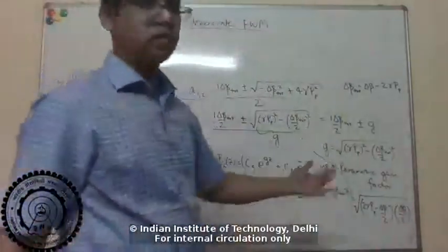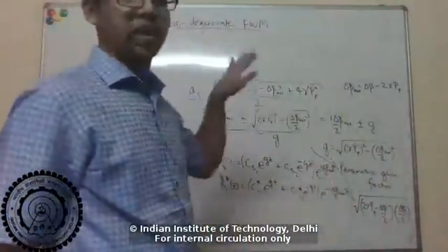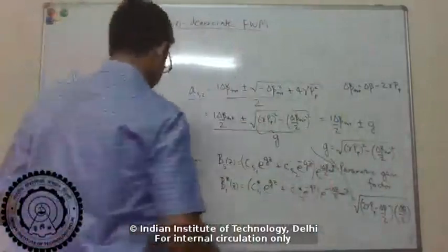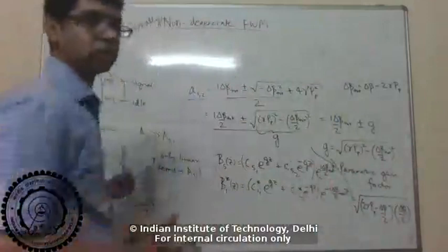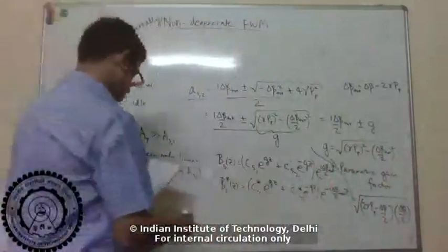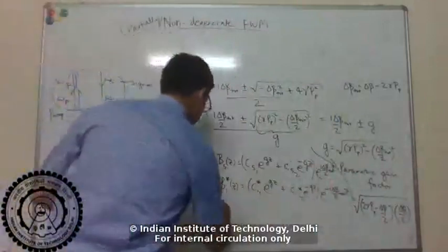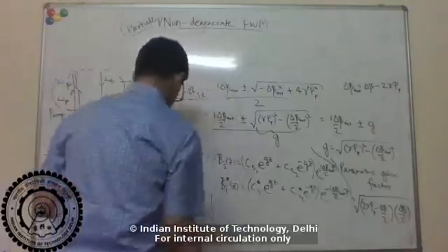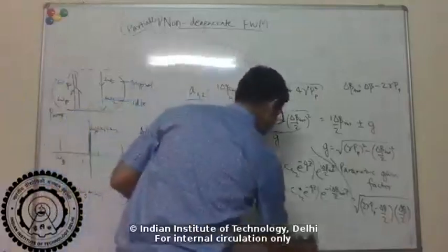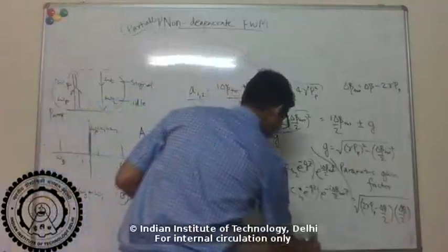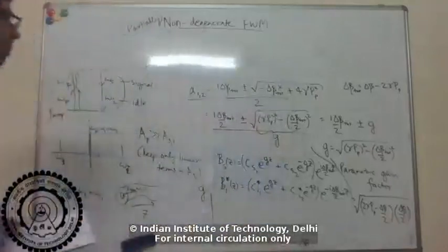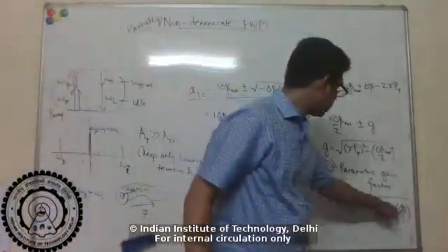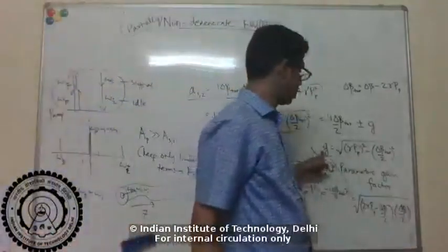Okay, so the delta beta depends on, for example, what waveguide you're choosing, how the refractive index varies with frequency, etc. Right? So the dispersion of the waveguide or the fiber. So if you plot this G versus delta beta, you can see at delta beta equal to 0, G is actually 0.